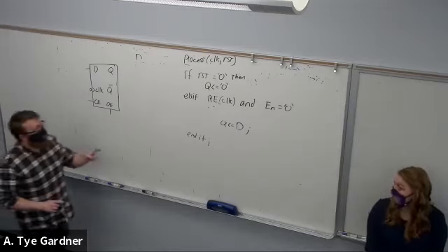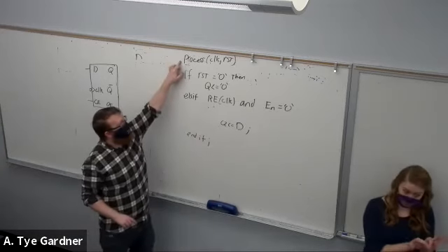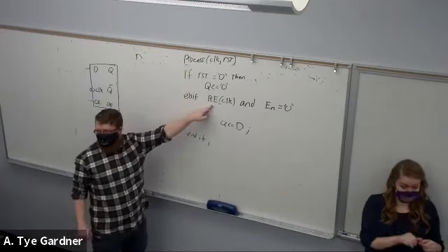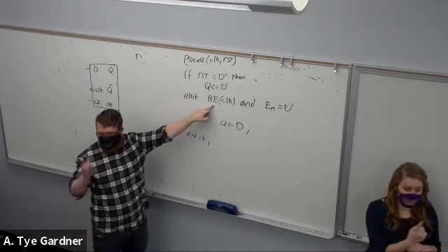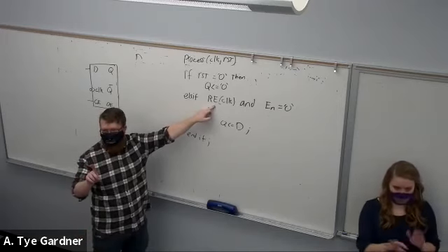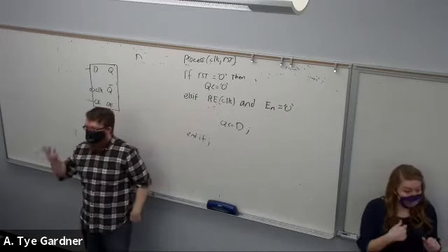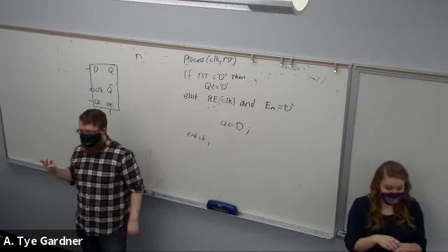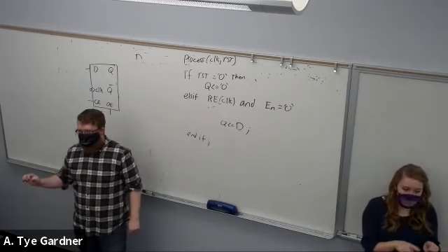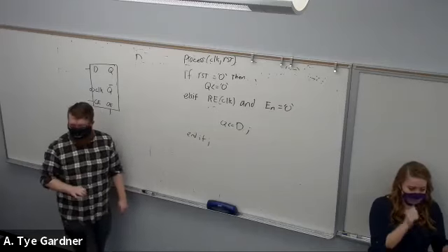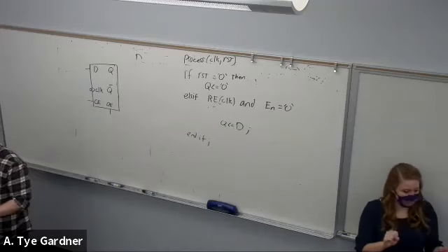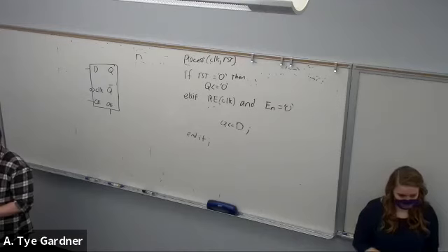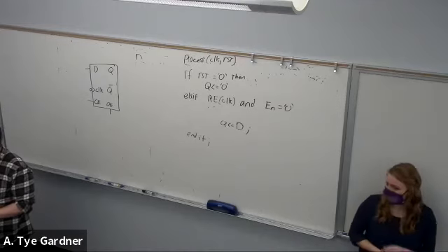Oh, it's also really important that inside of a process, never use more than one rising edge or falling edge statement. You only get one per process. You can have multiple processes inside the same architecture, but do not have multiple rising edges inside of a single process. So this just means you won't have more than one clock?